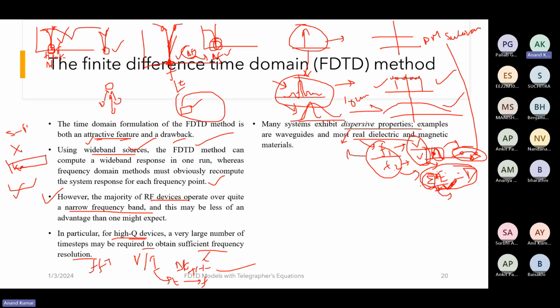You just have to do one convolution and then you get an expression which you multiply with the electric field, then you calculate the displacement current and update the electric field. What I'm saying sounds very complicated, but it isn't. It's fairly simple, but not as straightforward as in the case of frequency domain solvers.